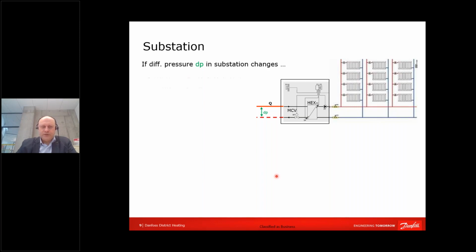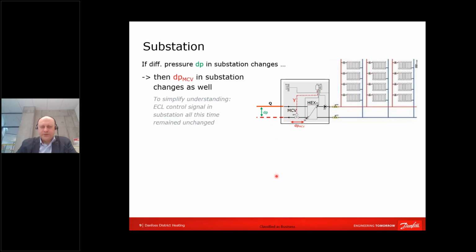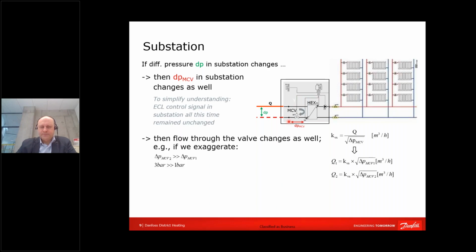So we can proceed further on. If differential pressure is changing across the motorized control valve, and just to simplify it, we mean that the controlling device, ECL, had not yet sent a signal to compensate for the pressure increase. So during that very moment, the flow through the valve is increasing.